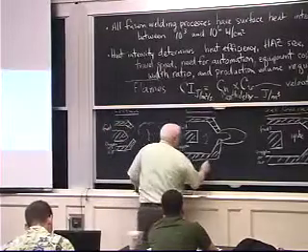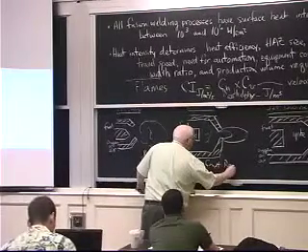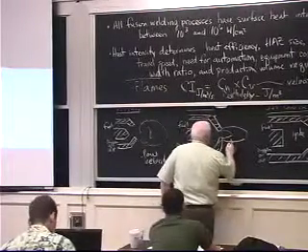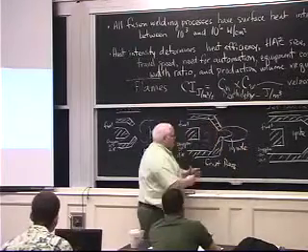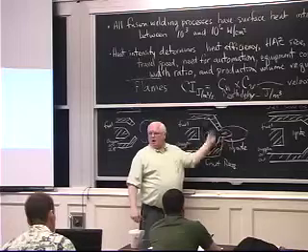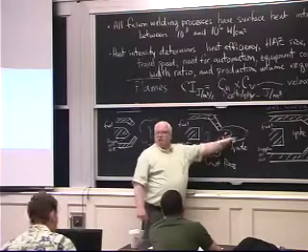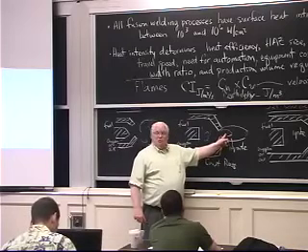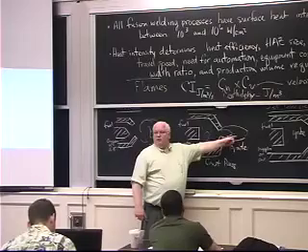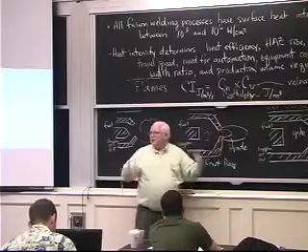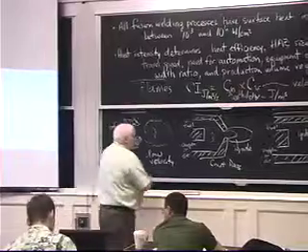Okay? So this is constant pressure mixing, but no ignition until I get out here. But when it ignites, it's already mixed. There's no need to diffuse oxygen, and so it burns with a nice uniform flame. And if you look at the flame, you'll see actual different regions. This might be a hotter region where you get carbon monoxide when you burn the hydrocarbon, and out here you'll burn the carbon monoxide, so you get kind of different layers to the flame, and there are whole books written on that. Okay? The velocity here,